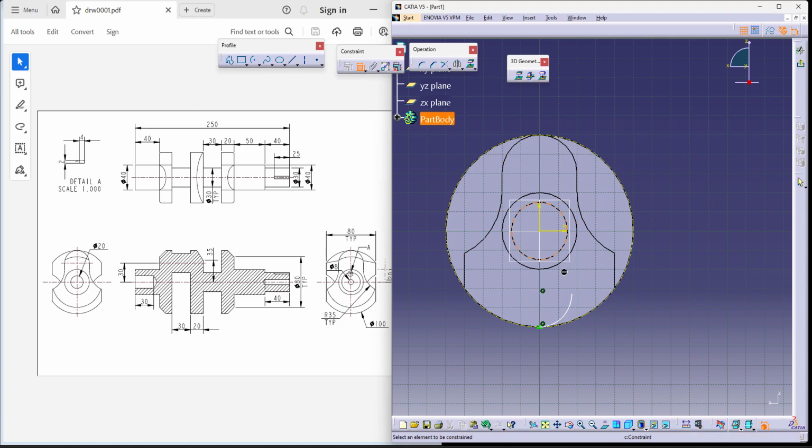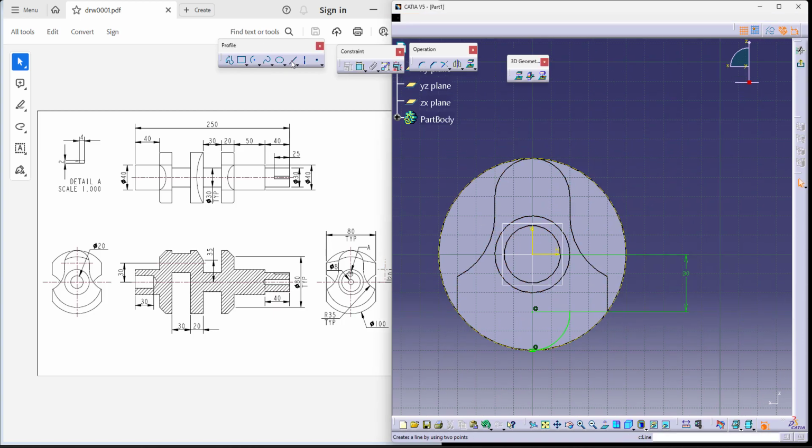Now we know that this is at a distance of 30, which we have already seen, which I've already shown you over here. Now, there is a straight line over here. I'm doing it the other way around as you have seen earlier. It's just the 180-degree rotation. You can save the sketch and also copy paste it as well. There's no problem. Now, I have an arc which goes this way, which again you already know, which we have already seen. That's again at 20 from the center. So let's try to take it at 20 from the center. And the arc diameter is 35.